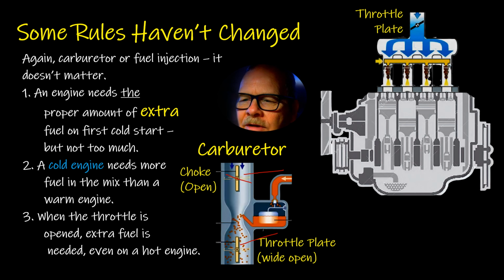Whenever you close that choke like that, when the throttle plate's closed, there's a little more low pressure there that's going to draw out of this fuel bowl through this venturi down in there. And incidentally, when it's idling, all the fuel that's going into the engine is going past the idle mixture screw that goes in, with that pointy end on it under the throttle plate, so you can adjust that, tune it out, and make it run real smooth.